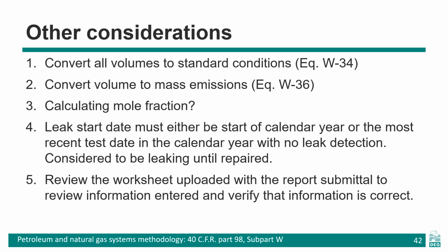Similarly, it's a good idea to check the calculations used for converting from volume to mass emissions and how mole fraction for the released gas has been calculated. Are these being done with a sample conversion spreadsheet that someone created 10 years ago, or do the individuals responsible for this data know what they are doing and why?